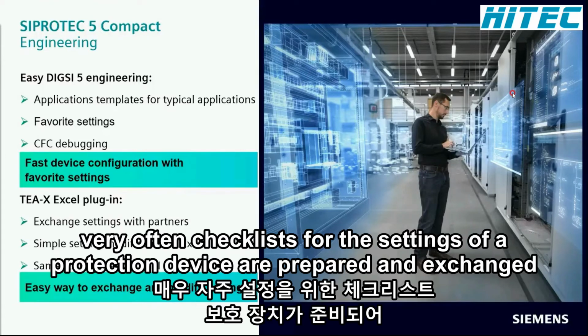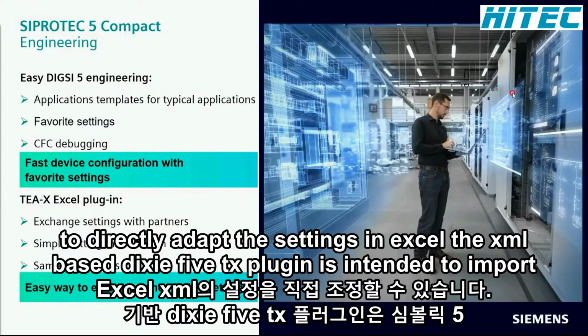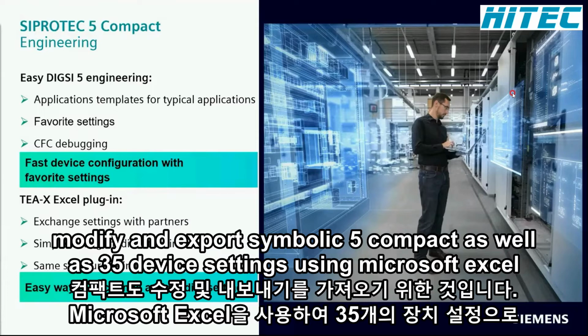Very often, checklists for the settings of a protection device are prepared and exchanged with the engineering department via Excel. With our TX plugin, you have the possibility to directly adapt the settings in Excel. The XML-based DXC5 TX plugin is intended to import, modify, and export SIPROTEC 5 Compact as well as SIPROTEC 5 device settings using Microsoft Excel.